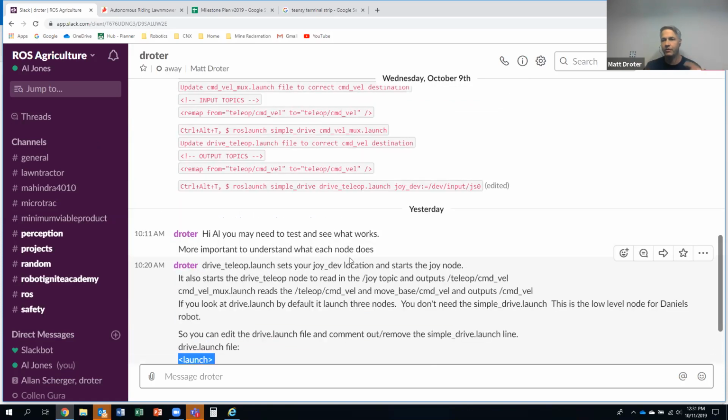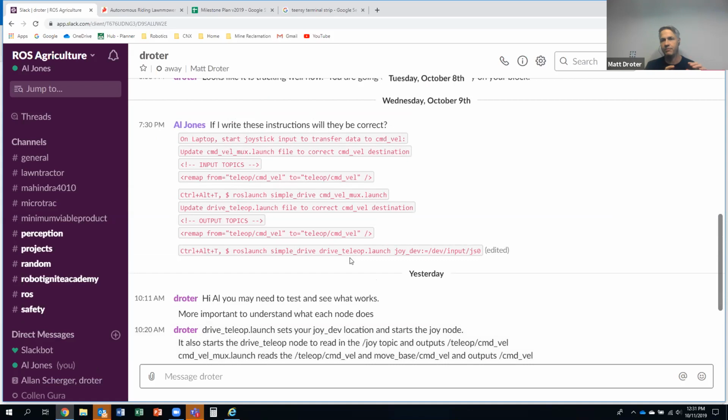So generally what happens is if you're working on a node, it's all from the command line, and then you'll just run the Python script. And then once that seems to be working okay and you've got it all debugged, we generally take that and move it into a launch file. And so then now you're starting it from a launch file. But as your robot gets bigger and you're adding more topics, instead of having 4 or 5 command screens open and then doing ROS launch, we start to combine those into one launch file. So everything goes from there.